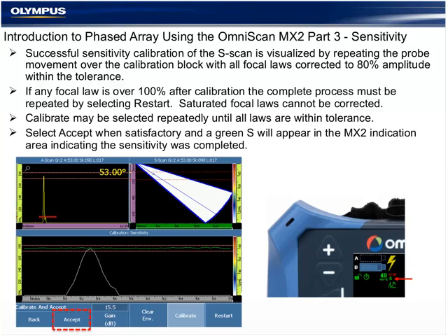The only reason that this window changes upon selection of calibration, where the line would not be within the tolerance, is because of couplant and pressure. It's directly related to amplitude, and you must maintain the same couplant and pressure. It's a very simple math equation the software is performing here, and it must use the same couplant and pressure to be able to complete the repeatability within the tolerance window.